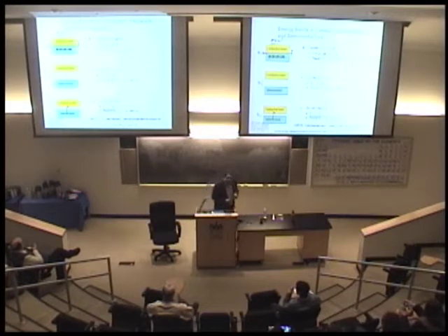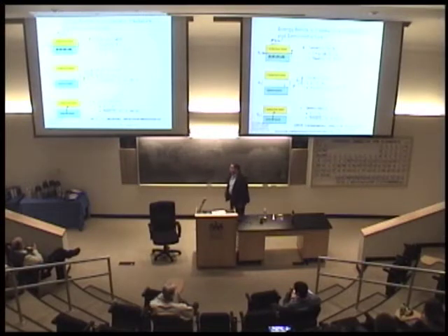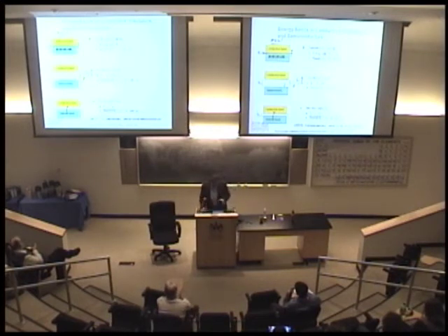But for the insulator, it's a big gap, and this goes like an exponential. The barrier it has to cross goes like e to the gap divided by the energy kT, all right? So if it's a couple of electron volts, it becomes an exponential barrier, so that insulators do not conduct, basically. Electrons cannot go to the conduction band. Okay? So every element has a different purpose in your CMOS device.